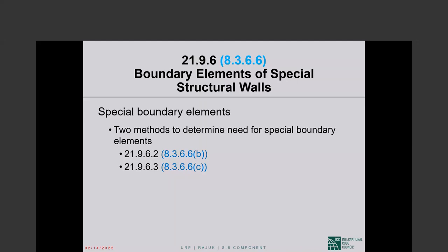That would be very expensive and time consuming, but much more importantly, much of that confinement won't do you any good. Because a shear wall has significant compression only over a small part of that 30 foot length. And where there is no significant compression, the confinement is not going to do you any good. It cannot do you any good.